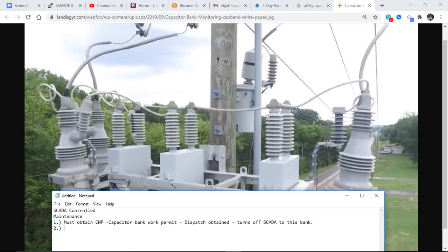All right. So the first step is you can do this by SCADA or manually at the pole through controls: open these vacuum bottles. Open vacuum bottles switch. That gives you the capability on all 3. You have to open all 3, one for each phase. That gives you the capability of breaking load inside a vacuum and not with the fuse cutout. Let's put over here 3, just to make sure you guys know. 3.